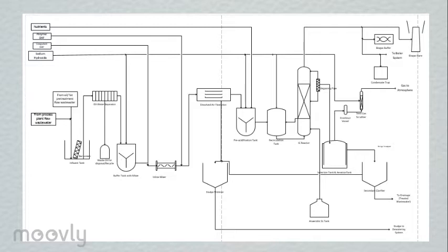After the wastewater is equalized in the buffer tank, it will be pumped to the dissolved air flotation unit, DAF, for further removing total suspended solids, TSS, and oil in the wastewater. Next, the process continues with anaerobic treatment. The wastewater will be treated anaerobically in a two-stage anaerobic process. In the first stage, the pre-acidification tank, the wastewater is partly pre-acidified. In the second stage, the IC reactor, the organic pollutants of the wastewater are converted into biogas.